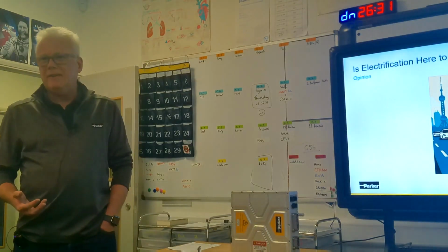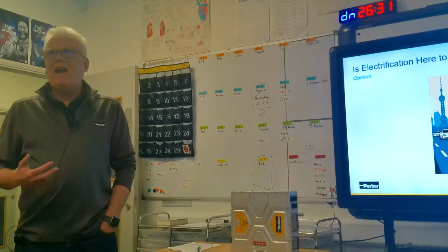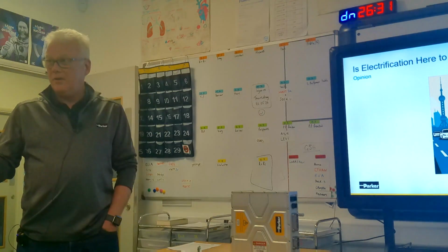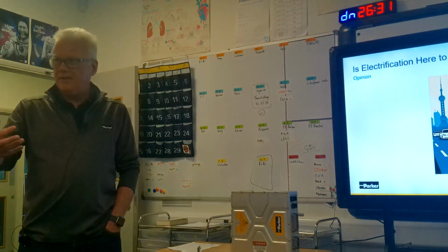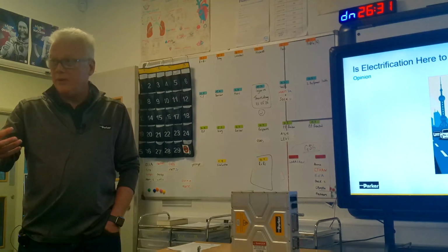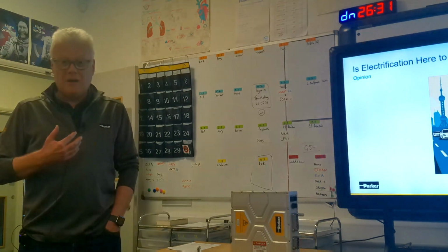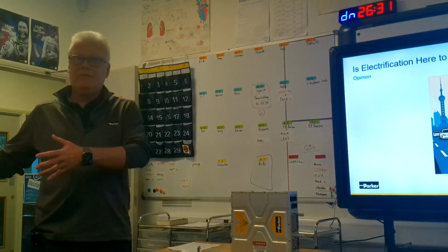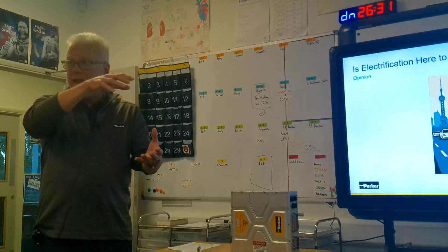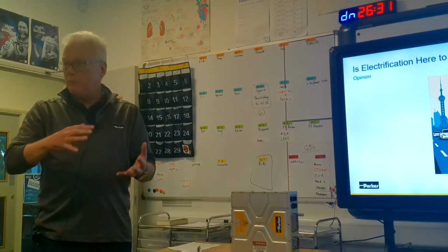So this was another question that was asked. Basically, can you use a permanent magnet machine as a generator? Yes, you can. Like I said, you can control torque by controlling, say, the Q-axis current. If I make the Q-axis current positive, I'll make a positive torque, and I'm motoring. If I reverse that and make it negative, then I'll make a braking torque, and I'm regenerating. All that energy will flow from the vehicle into the battery and charge the battery back up again. Yes, you can capture that energy from braking, absolutely.